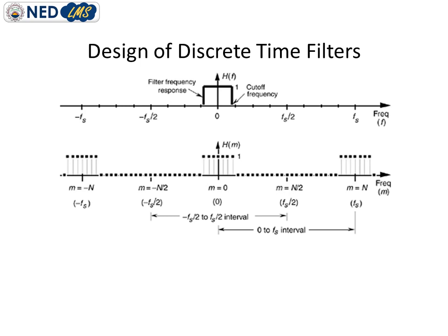So the technique we are utilizing here will give us the FIR filter coefficients. Please remember, if we convert this discrete frequency response into an impulse response by taking the suitable Fourier transform, then we will actually obtain the FIR filter coefficients.